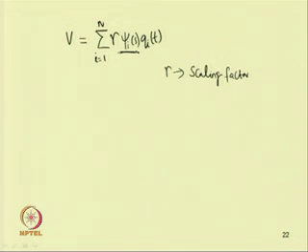So, one can take the psi as either an eigenfunction, or a comparison function, or an admissible function. In case of the eigenfunction, the shape function satisfies both the boundary conditions and the governing differential equation. So, eigenfunction satisfies both the differential equation of motion and the boundary conditions.